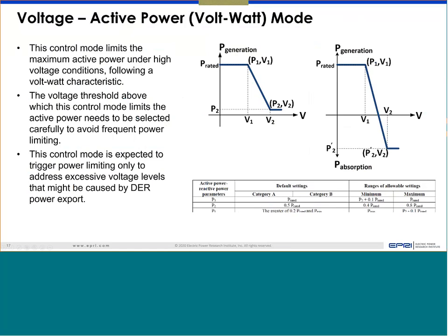So basically, energy storage can start reducing its discharge, going all the way to zero discharge. If the voltage still continues to go high, which means excess generation, they can start charging to help regulate the voltage. So if it's energy storage which was discharging at high voltage, it can start reducing discharge, which effectively reduces the generation, go all the way to zero.